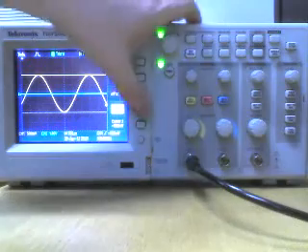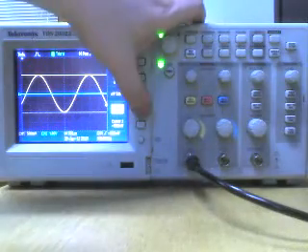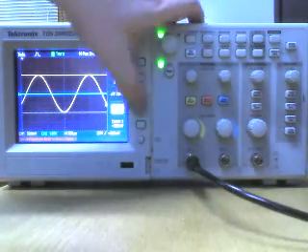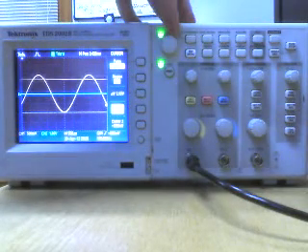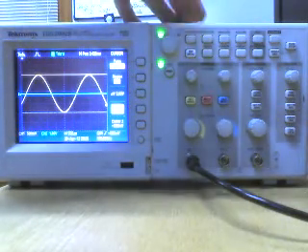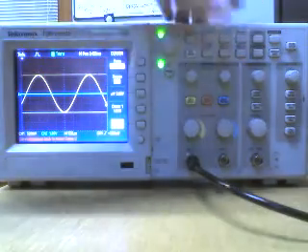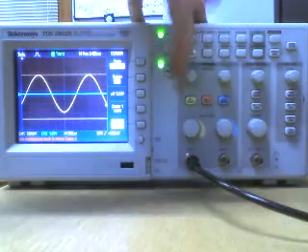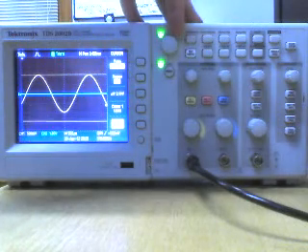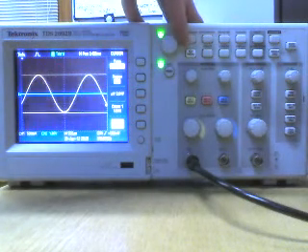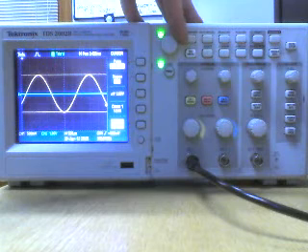Usually they're not. If you want to measure your waveform, you select cursor 1 and this knob lights up, and you can move the top cursor to the top of the waveform. Cursor 2, I mean, not channel 2, you can move the bottom cursor about the screen until it's at the bottom of the waveform.